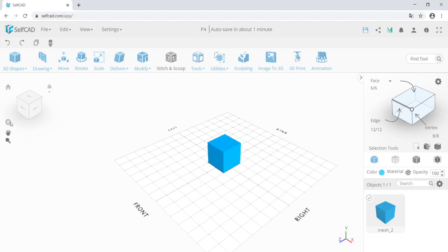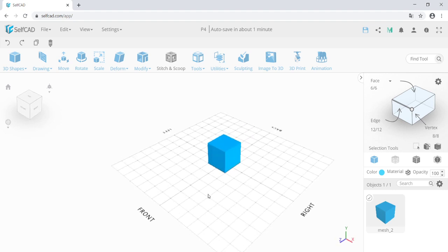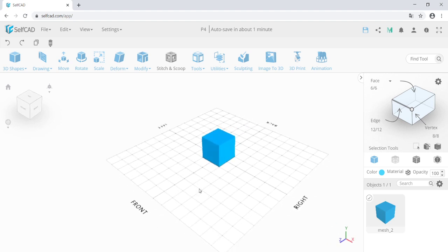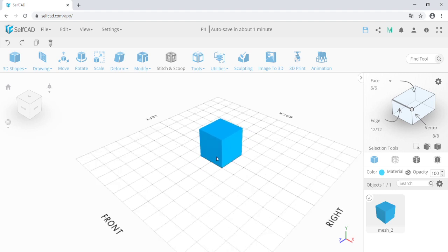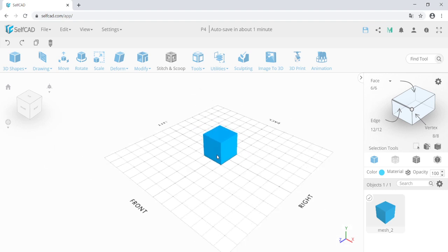While modeling, I leave rotation enabled as it is. For pan, I'm using the middle mouse button or keyboard arrows. For zoom, the mouse wheel. Now let's take a look at the object list. On the right side panel, you can see the snapshots of all the objects that are currently in the scene. The cube is by default selected. To deselect it, uncheck the selection mark, click on the mesh or on the workspace. You should also notice that checking the selection mark or clicking on the mesh results in selecting it.